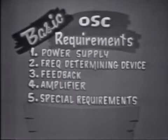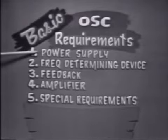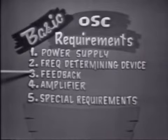There may be other requirements depending on the application of the oscillator, which you'll discover when you study a particular piece of equipment. But the main idea is that all oscillators are basically the same. So whatever the type or the name of the circuit, all oscillators will require a power supply, a frequency determining device, and feedback, usually from an amplifier.